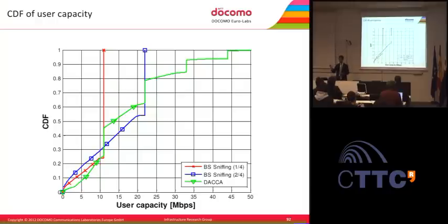And the reason the curves are stepped is because there should be 6 steps, depending on the amount of component carriers we use. So basically, when you use only 1 component carrier, this is the highest capacity you can reach, because we use a truncated Shannon bound model. And when you use 2 component carriers, this is the capacity you can reach, then 3, 4, and 5.